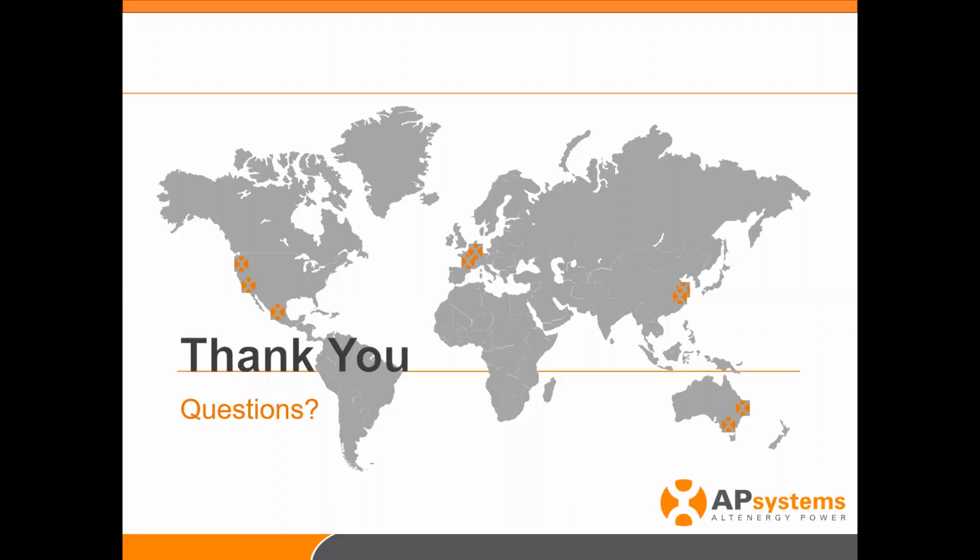Okay, and someone had asked regarding the setup of the ECU, if they can scan all the codes in the office before mobilizing, and that's a big yes. Like Chris was saying, you just plug in that ECU at the office. You can actually connect all those before you even get to the site. It's a pre-configuration if you want to have that plug and play at the site, but again, on site, as Chris was saying, using the ECU app to verify that those microinverters are talking and ready to produce energy. That's the critical part. Absolutely, good question.